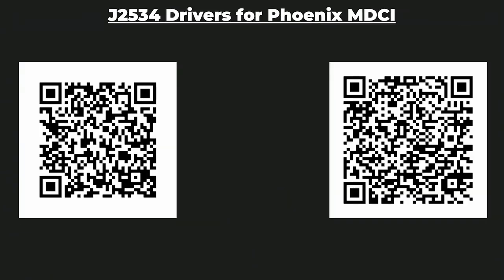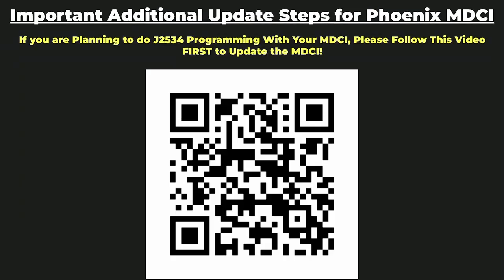So if you're looking for the drivers for the MDCI that goes with the Phoenix Max or the Phoenix Smart, you can try both of these links. Those drivers get installed on your PC before you install the vehicle manufacturer software. You also need to make sure that you plug your MDCI into the wall and power it up, and also plug it into Ethernet directly to your router. Now, why are we doing this? Because the MDCI will also download additional updates for the hardware via this particular route.